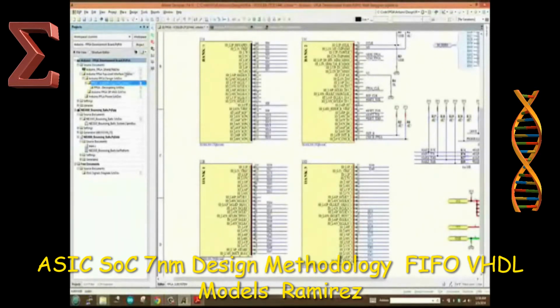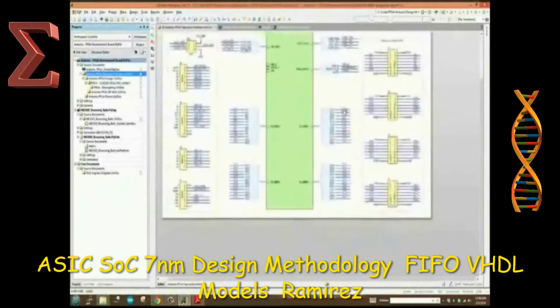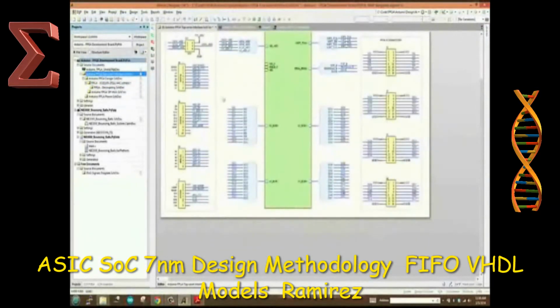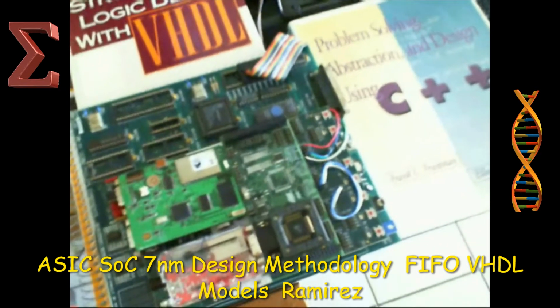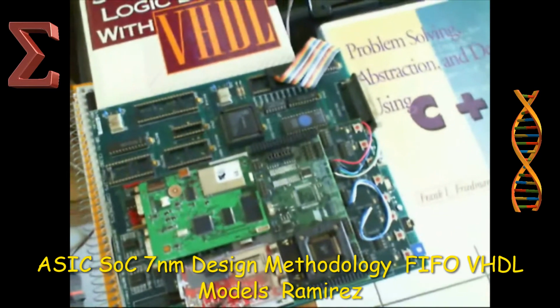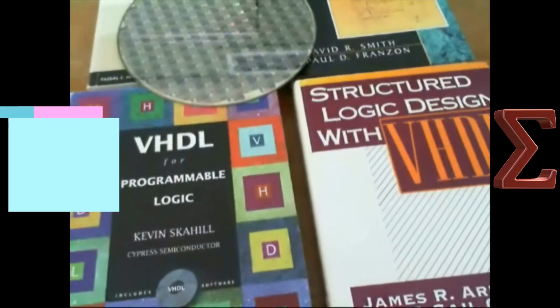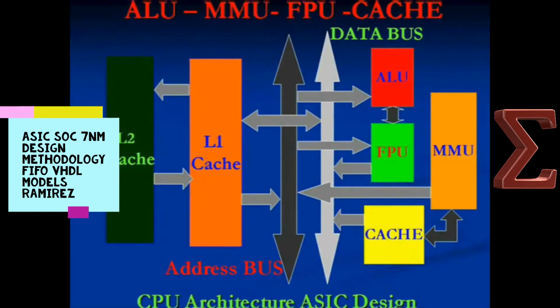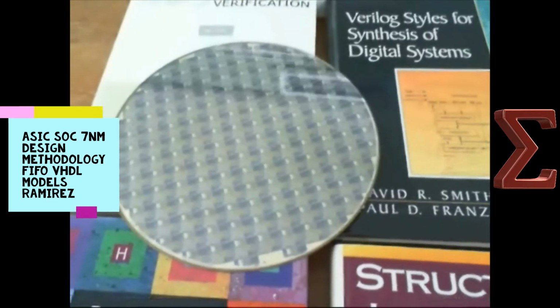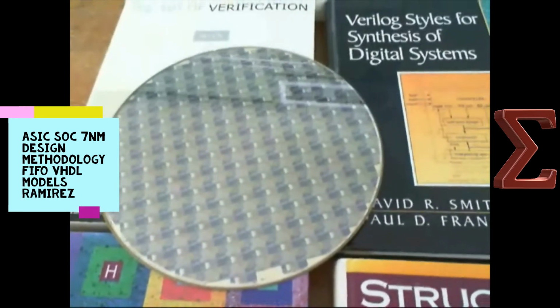I describe the design in RTL, register transfer level, and capture the timing constraints of this design, and also the behavioral description of the design, using the HDL, in my case Verilog or VHDL, as a hardware description language.